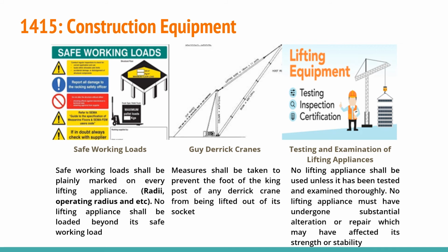Testing and examination of lifting appliances. No lifting appliance shall be used unless it has been tested and examined thoroughly for everyone's safety. No lifting appliance may be used if it has undergone substantial alteration or repair which may have affected its strength and stability, unless it is re-tested.